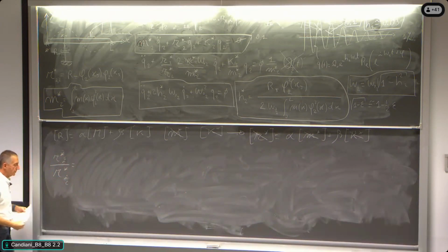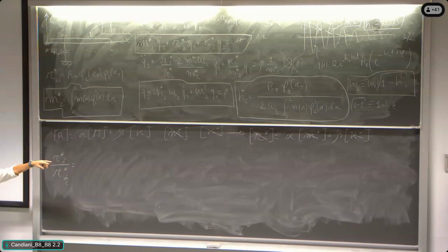So we have to deal with what is intrinsically meaningful for the damping, not the dimensional damping, but the non-dimensional damping. And so we must write things in terms of non-dimensional damping associated to the mode i, given the hypothesis that we made. And so we have to divide by the critical damping.